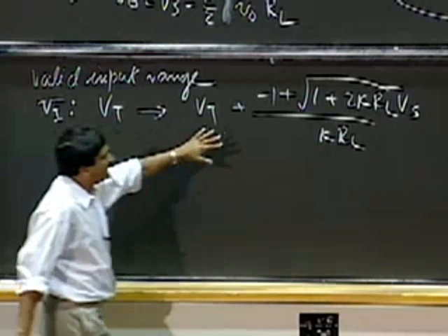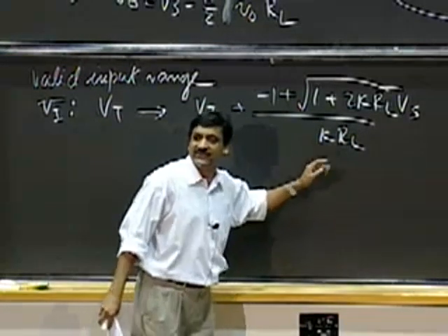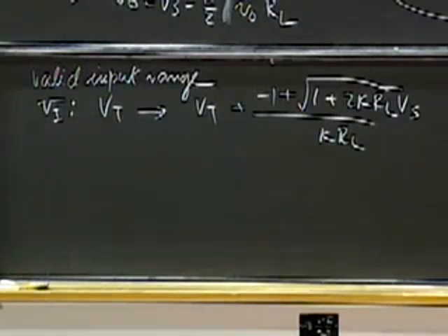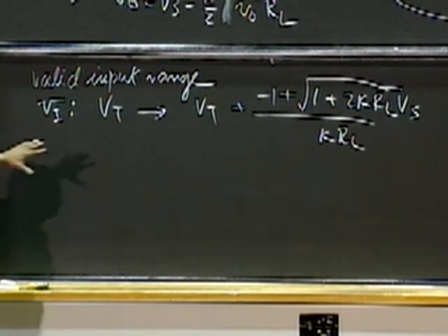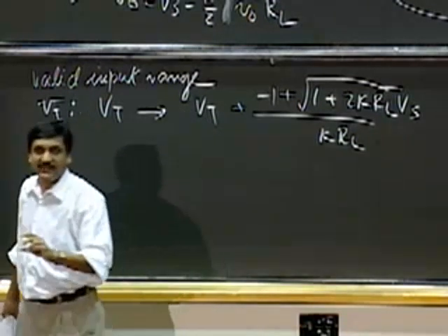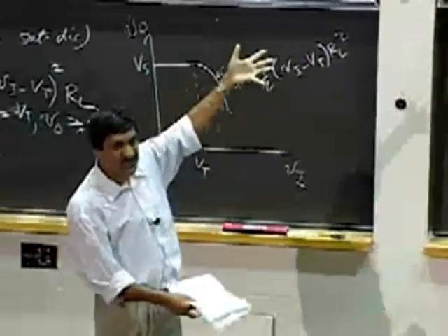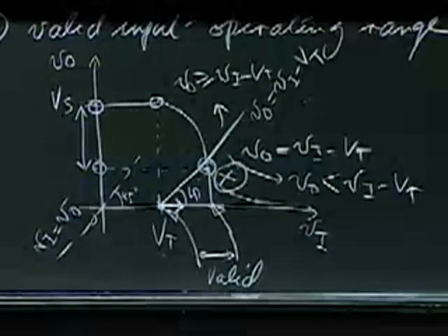And again, I won't dwell on this equation because you will get a different set of limits for other devices, for other circuits containing a MOSFET, or for other outputs that one may be focusing on. What's more important here is not so much the results that you see, but the process that I've gone through. How did I get here? The way I got here was I looked at the graph and said, look, the MOSFET is in saturation in that regime, and I'm finding the bounding points of the regime of saturation operation.